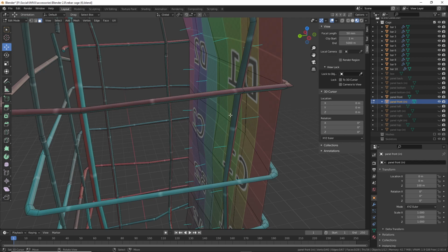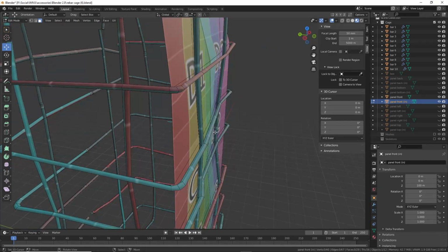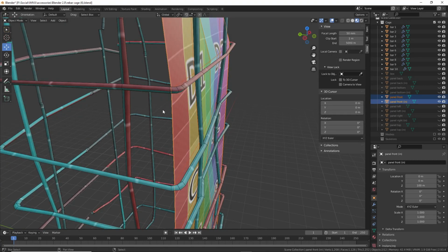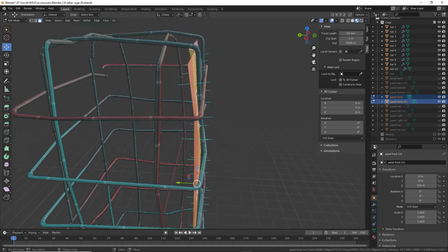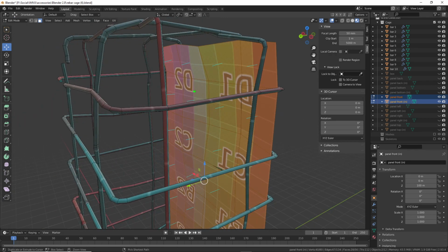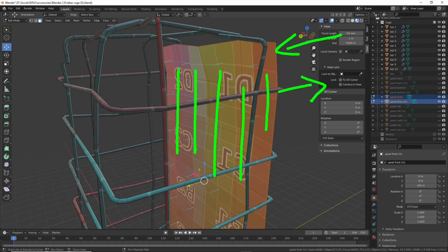For the normal maps, because we can see both sides of the mesh, this is something we'll have to start doing. So let's select both of them. This is something we'll have to start doing for true, air quotes, true double-sided meshes, because that's the only way to ensure the lighting or the normal map appears correctly on the inside of the mesh. If our lighting source is coming from this side, the normal maps on the outside are responding to the lighting from that orientation.